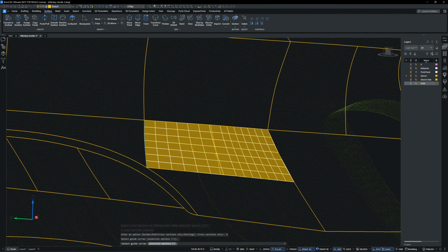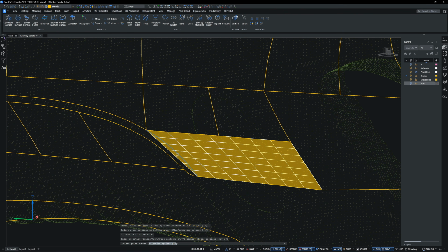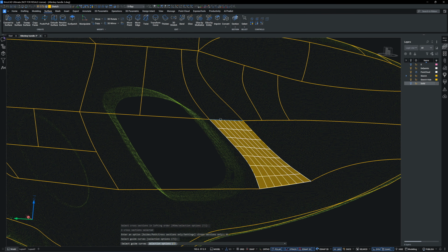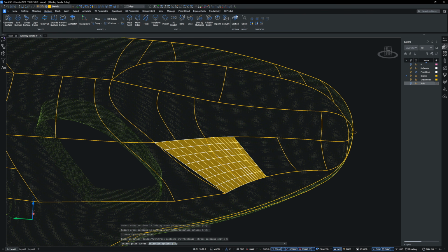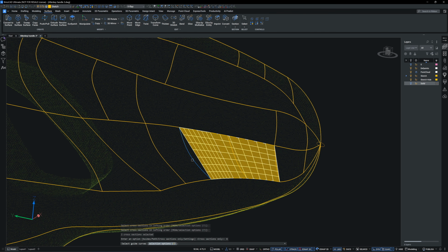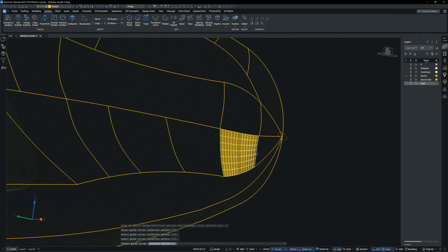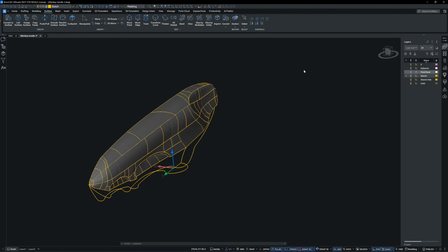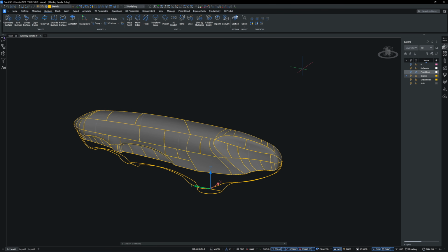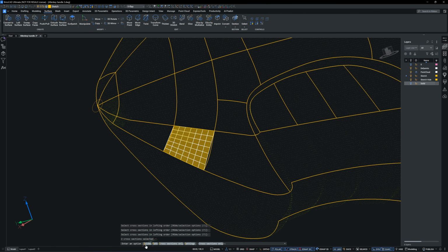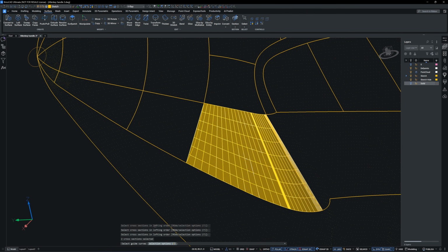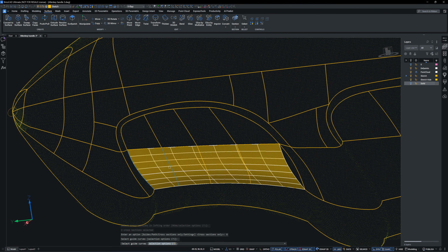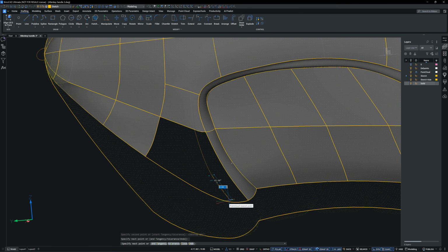The workflow for reverse engineering with surfaces is very straightforward. Start by creating 2D sketch frames, then build 3D splines for the guide rails by snapping control points directly onto the point clouds. Test each lofted surface segment to determine where boundaries should be broken and how many guide rails are needed. Once the 3D curves are complete, retrace the spline if necessary to achieve a smoother continuous curve.